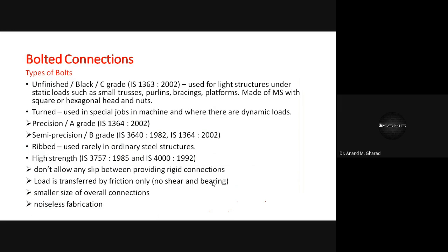Then these are very good type of bolts which are known as high strength bolts. The advantages of high strength bolts are they don't allow any slip, providing rigid connections. They are slip resistant. Then the load is transferred by friction only. There is no shearing and bearing. Okay. So you must be aware of this term shear. Are you aware of this term bearing?